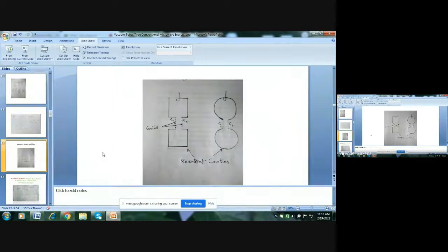So this type of cavities are used. These are called re-entrant type cavities, meaning the walls of the cavity at the center are very narrow, so that the interaction time is very small. So this is the rectangular re-entrant cavity, and this is the cylindrical re-entrant cavity. These are two grids, G1 and G2. Between these two grids, the RF field and